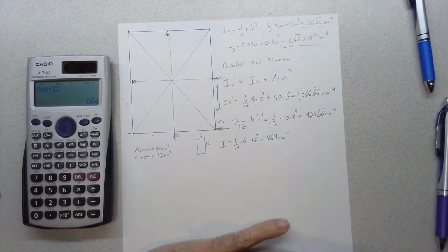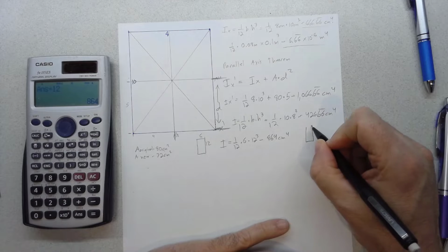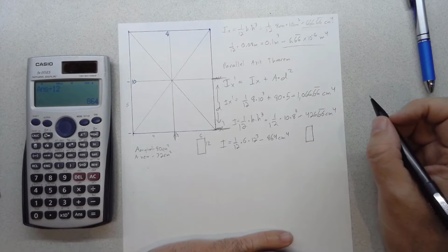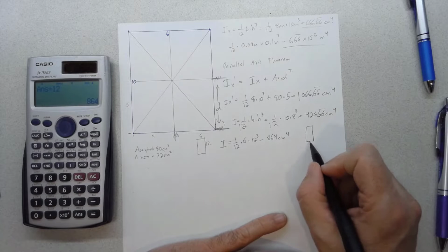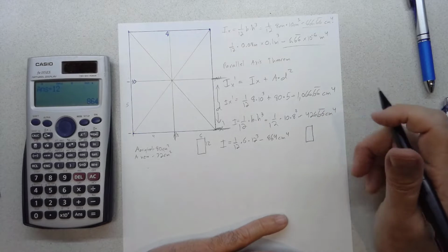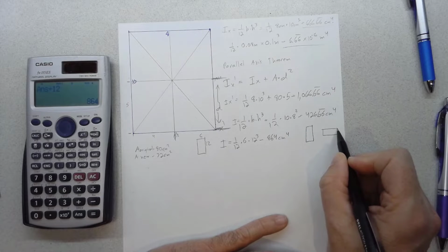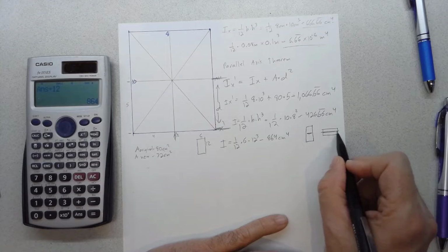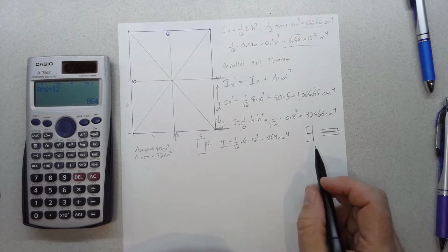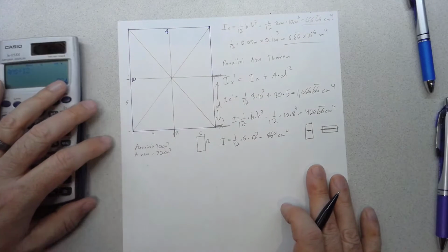In original wood construction, you would see lots of beams, right? Just nice straight rectangular beams because they're easy to manufacture. And when you do that, you see beams installed vertically, right? With the longer dimension in the vertical direction as opposed to the horizontal direction, because it's much stronger in this direction of bending, where you're bending about the short dimension versus where you're bending about the long dimension there.